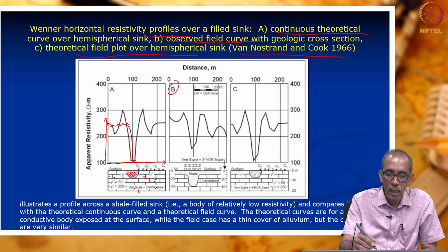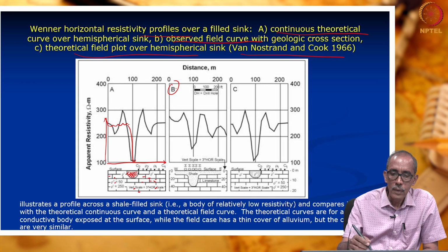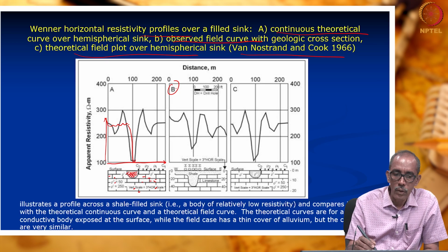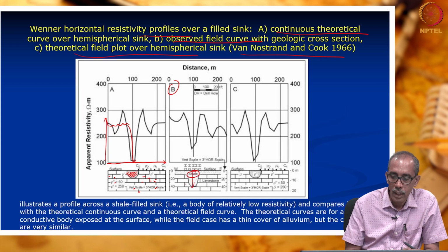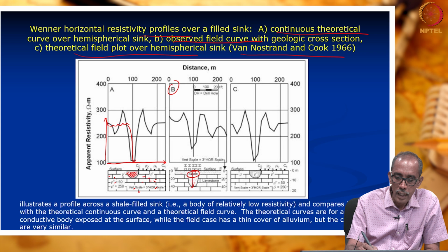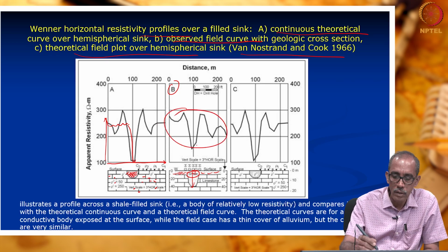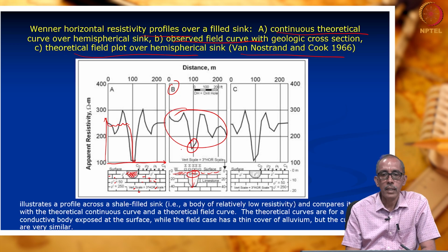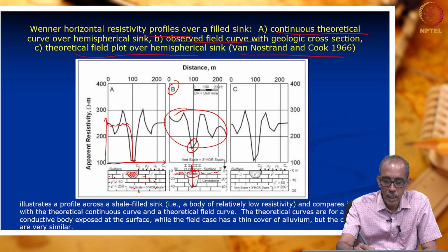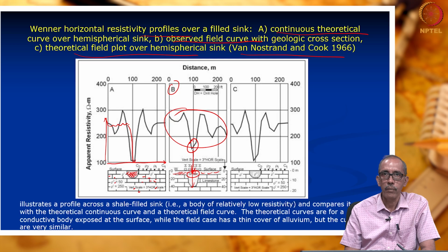Similarly, here on B, we have carried out a similar study where the thickness of the shale is much more. Further, the same low resistivity formation also extends to either side. That can also be brought out by the resistivity profiling. What is very evident is this low resistivity measurement here, indicating that just beneath it you have the low resistivity zone.